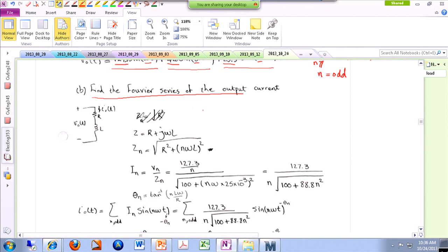All right. So now we are looking at our load. Our load is an impedance network of a resistor placed in series with an inductor. So if you look at the impedance of them, the impedances are being added with each other. The impedance of the resistor is just R. The impedance of the inductor is j, which is the square root of -1, times omega times L. All right. Now, if I am interested in evaluating this impedance at a particular frequency, I have to consider this equation.